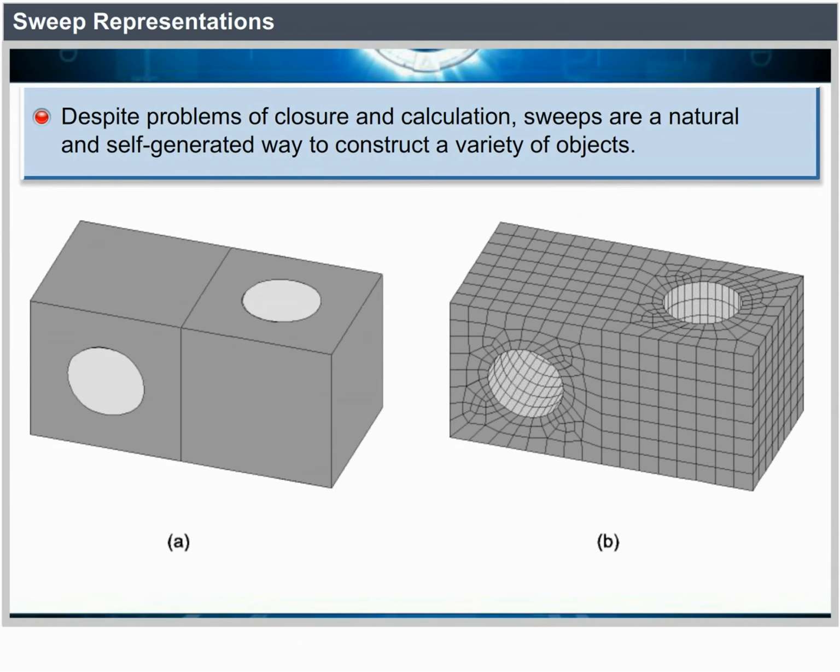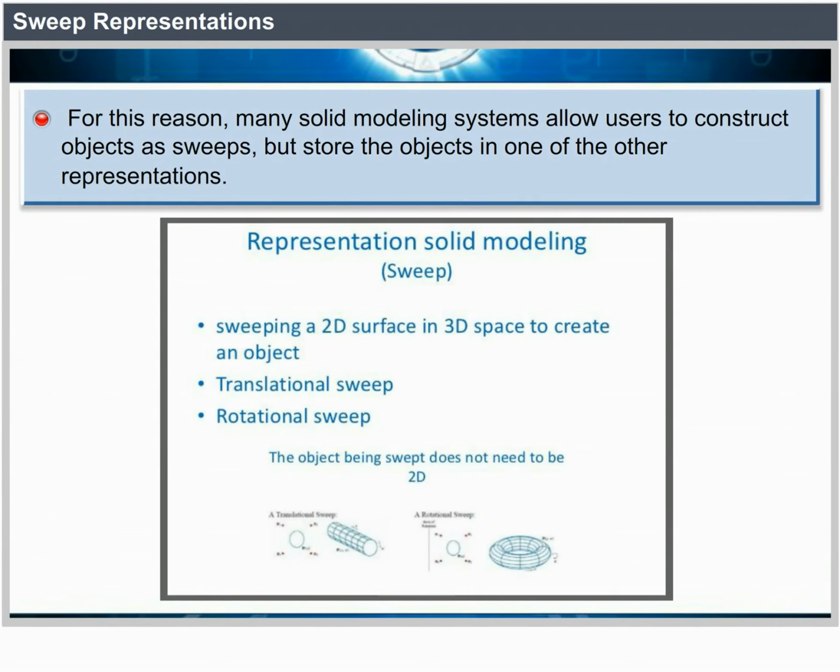Despite problems of closure and calculation, sweeps are a natural and intuitive way to construct a variety of objects. For this reason, many solid modeling systems allow users to construct objects as sweeps, but store the objects in one of the other representations.